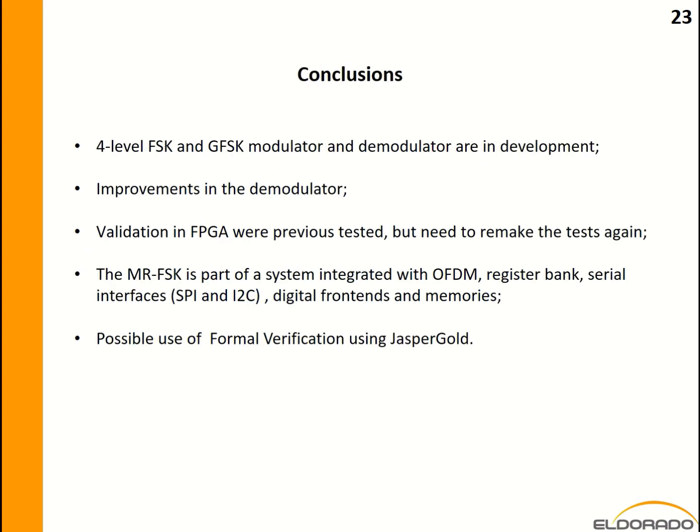Conclusions. 4-level FSK and GFSK modulator and demodulator are in development. We are making improvements in the demodulator to reach better performance. Validation in FPGA was previously tested, but the tests need to be redone. The MRFSK is a part of a system integrated with OFDM and other blocks. Possible use of formal verification using JasperGold.